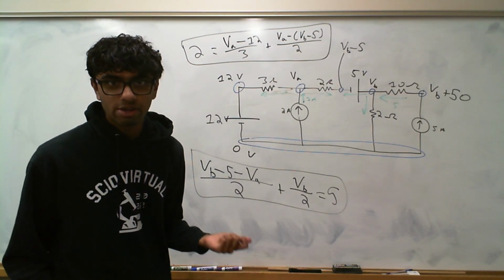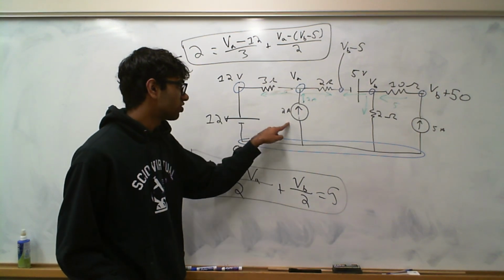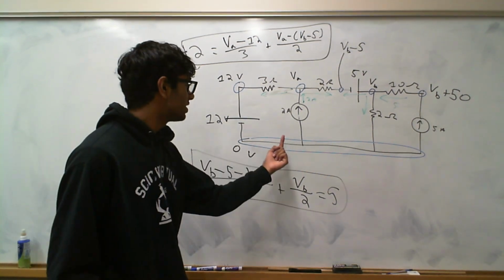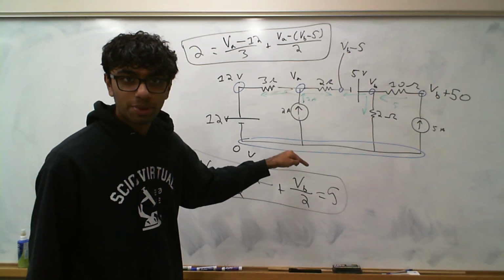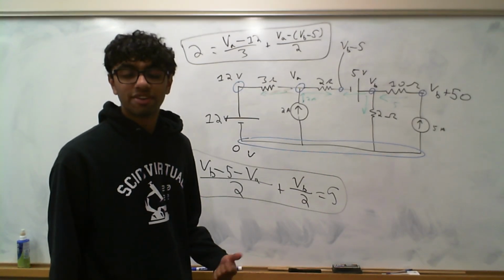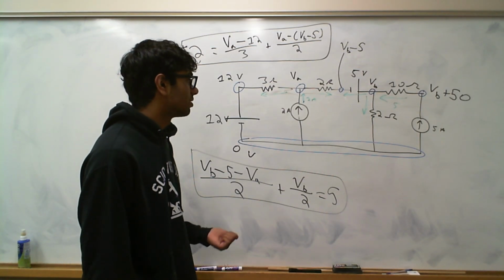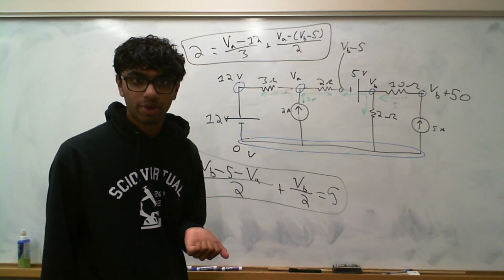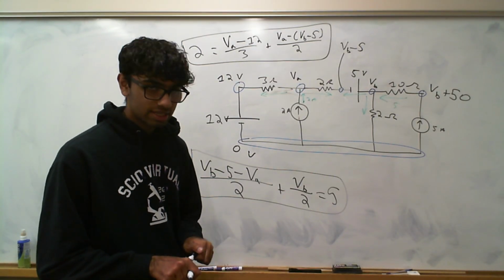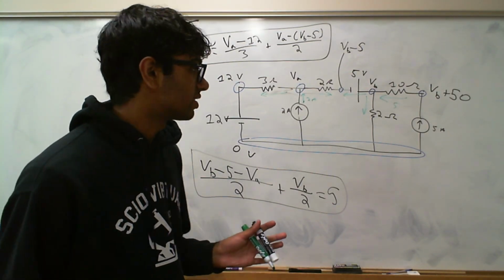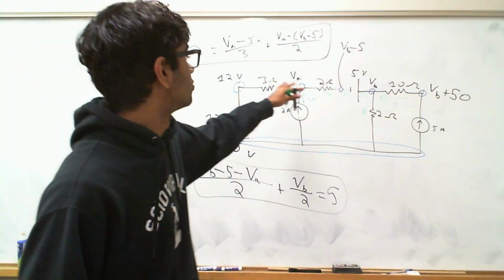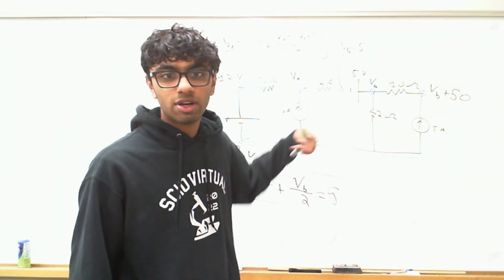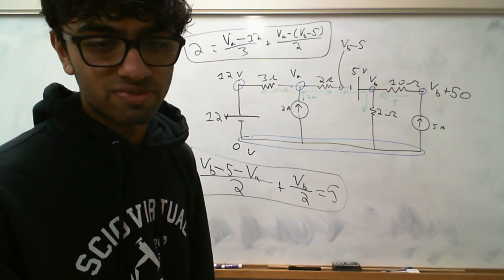If it does, then that battery absorbs power. For a current source, is voltage gained opposite the direction of current flow? If so, then this current source absorbs power. Okay? So that is that problem. It's not as bad as it looks. Just remember, all you need to do is find each node, write the voltage at each node. That's the same prescription for every problem.